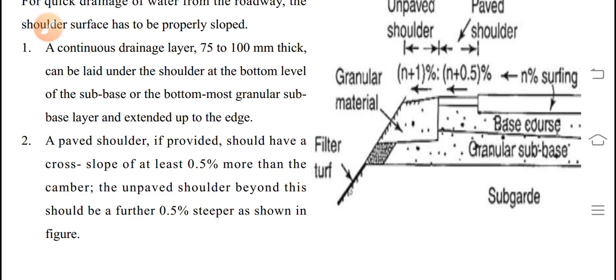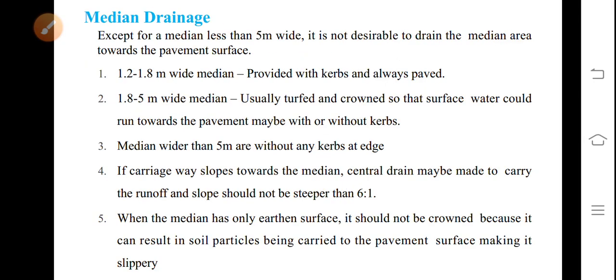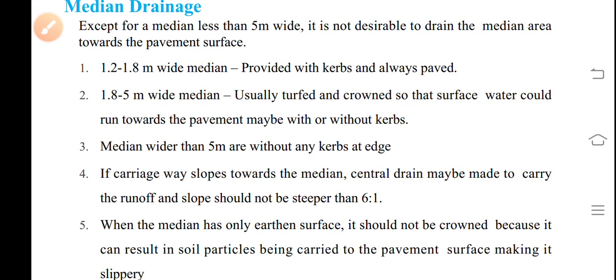Very gentle sloping of camber. Median drainage. Except for a median less than 5 meter wide, it is not desirable to drain the median area towards the pavement surface.